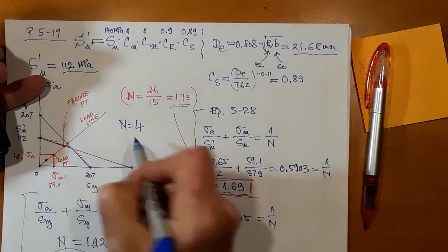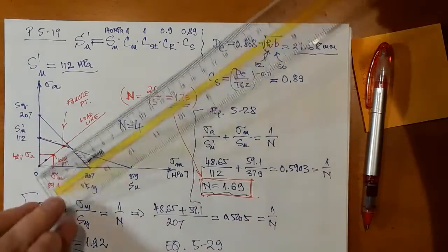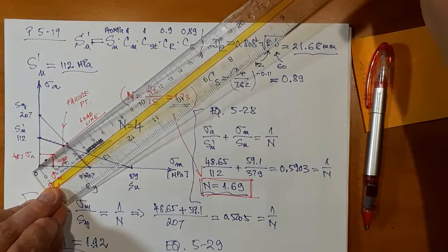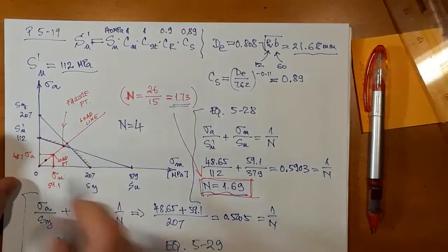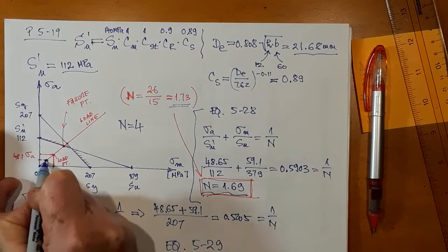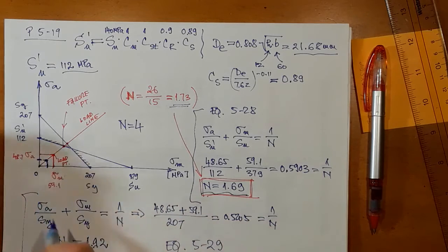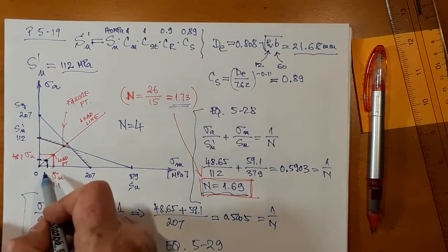That's 6.5. So I measure 6.5 millimeters. This should be the load point for a design factor of 4.